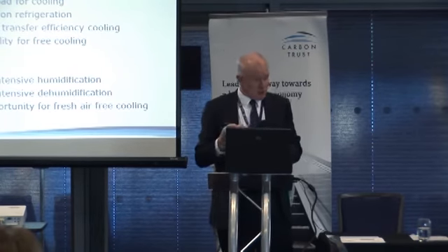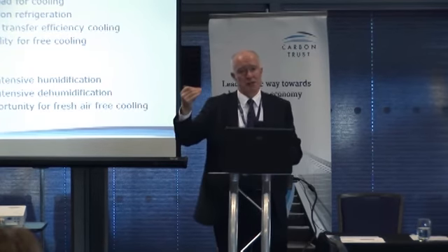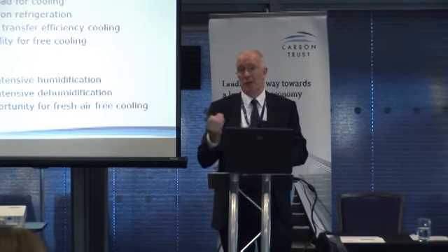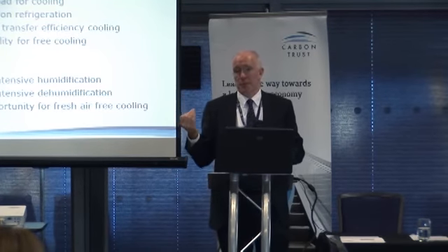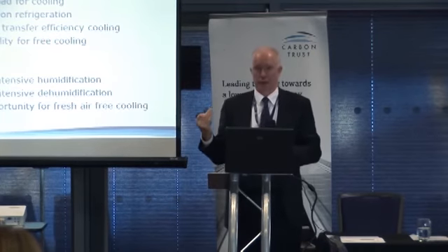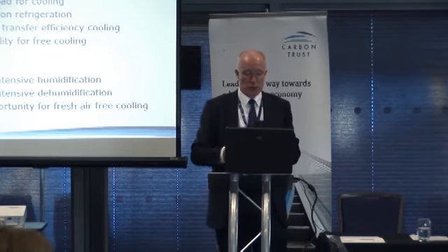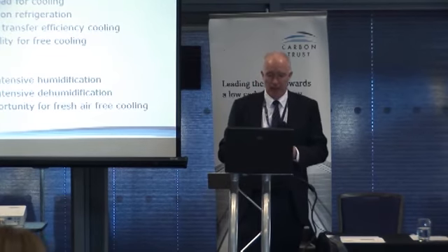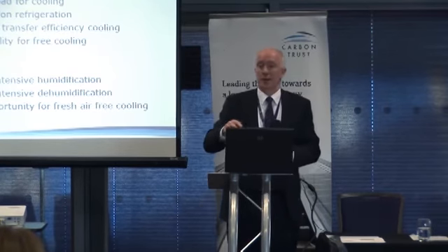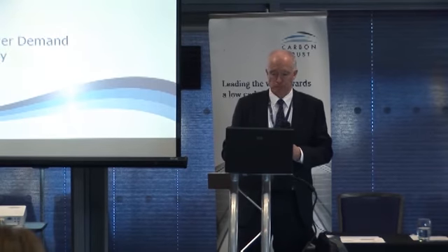And the other thing is, as you increase the temperature from perhaps 18 up to 24, 26 degrees centigrade, you vastly increase the opportunity to use free cooling from the fresh air outside, because we now have a much warmer room, and therefore the fresh air can do natural cooling rather than have to engage with refrigeration. And that's a very big opportunity as you start to float these things up. And again, in terms of humidity relaxation that most people have already done, it obviously increases the use of free cooling as well.